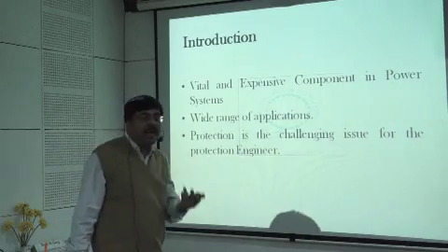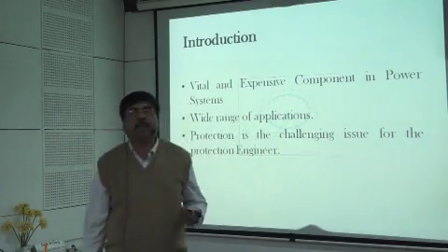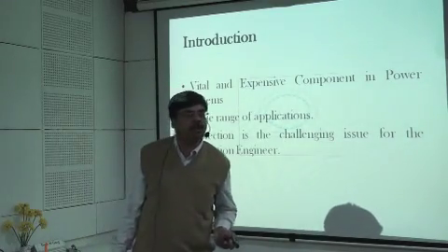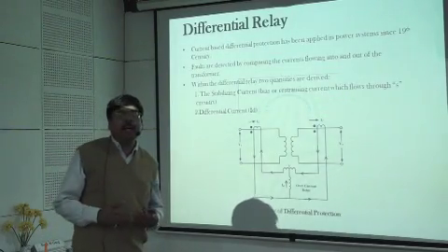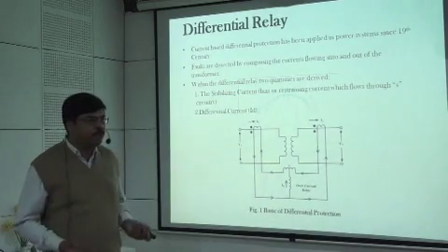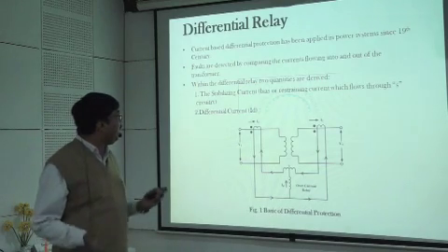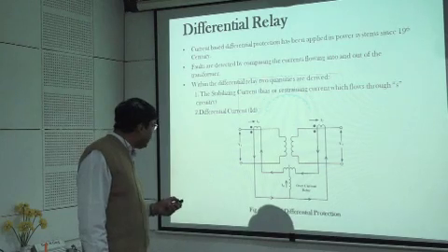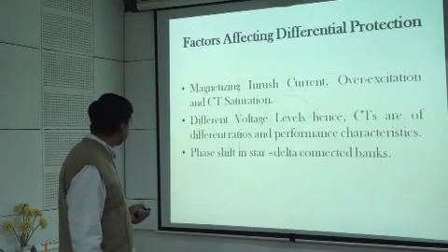Transformer is a vital and expensive component of electrical power system and hence it needs adequate protection. Protection of a power system is a challenging issue for a protection engineer. For providing protection to transformer for internal faults, the differential scheme is being used where the faults are detected by comparing the currents flowing in and out of the transformer. In differential, mainly we have 2 circuits, differential and the restraining or the stabilizing circuits.